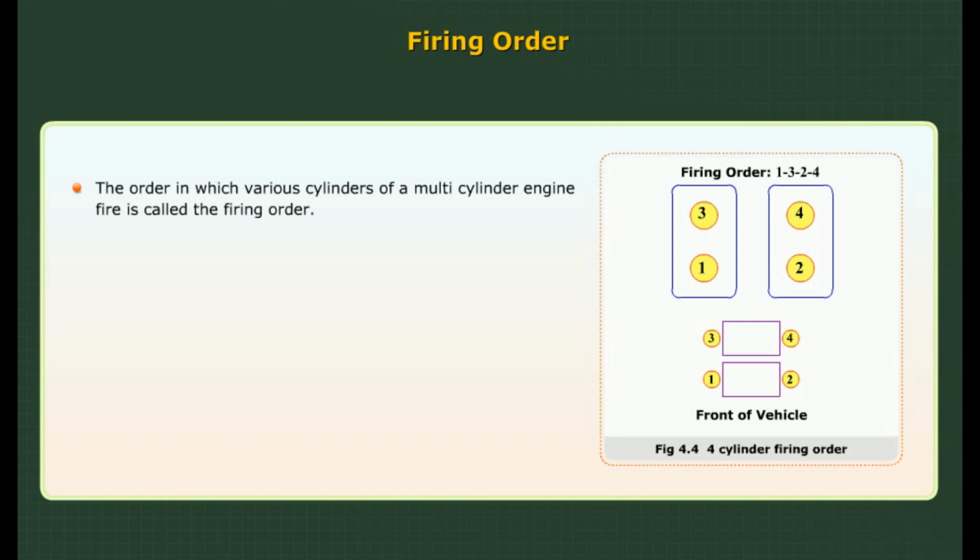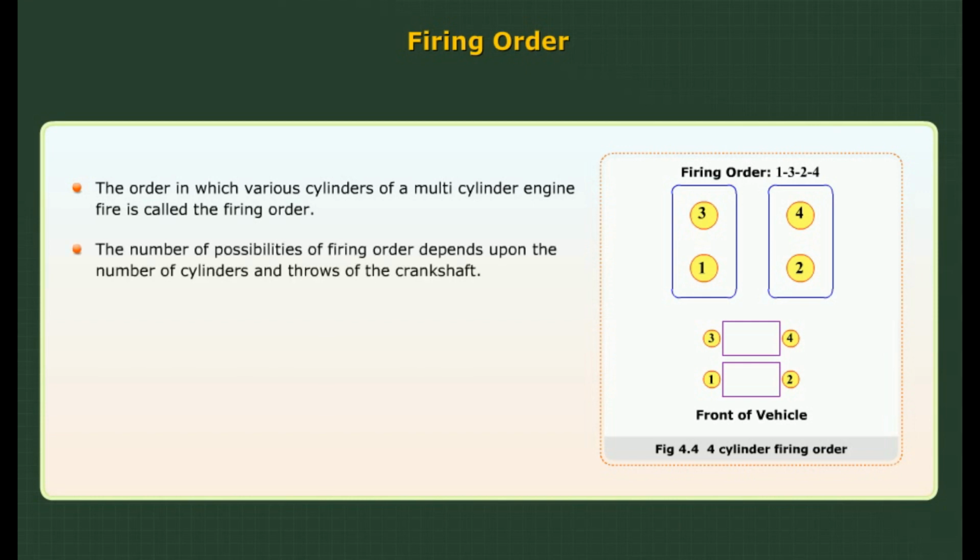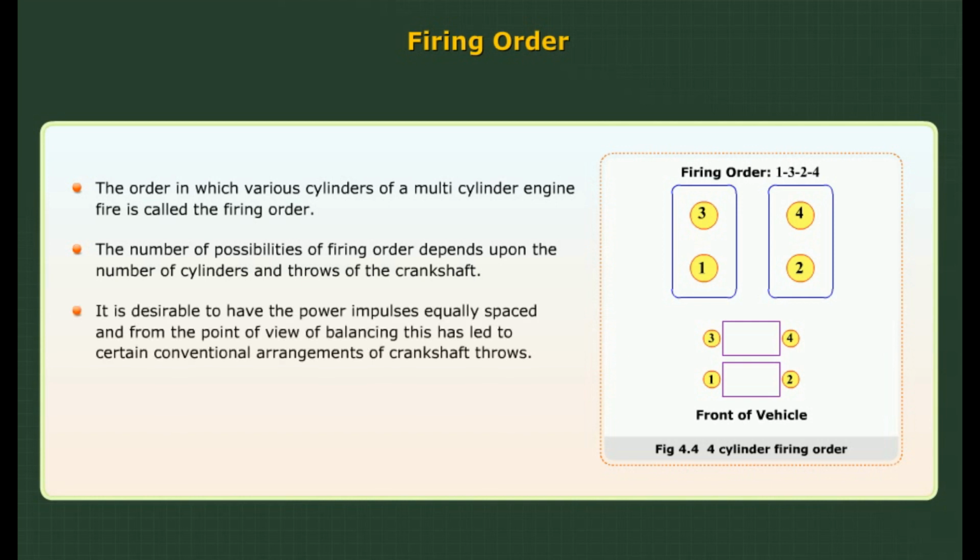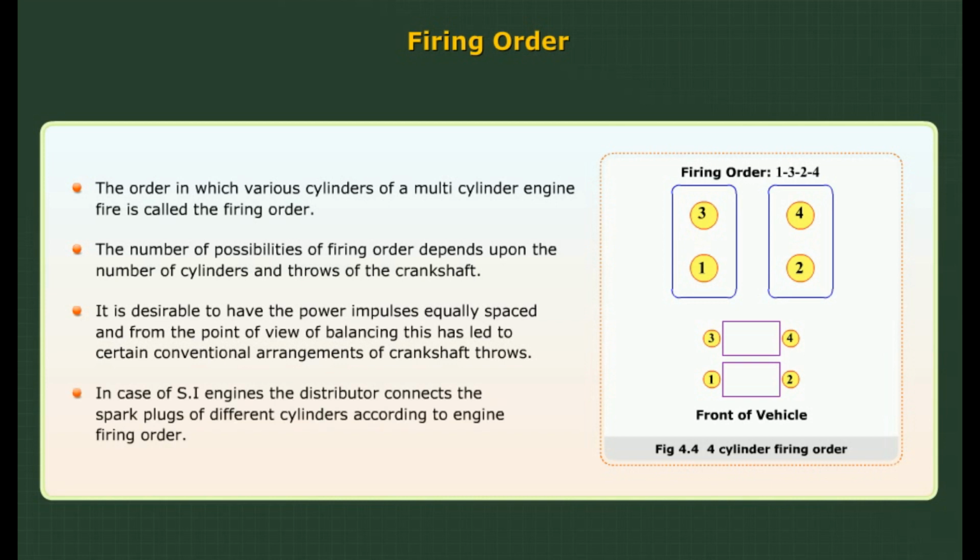Firing order. The order in which various cylinders of a multi-cylinder engine fire is called the firing order. The number of possibilities of firing order depends upon the number of cylinders and throws of the crankshaft. It is desirable to have the power impulses equally spaced, and from the point of view of balancing, this has led to certain conventional arrangements of crankshaft throws. In case of SI engines, the distributor connects the spark plugs of different cylinders according to the engine firing order.